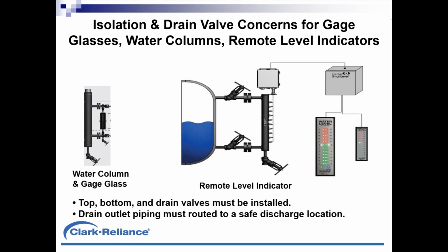Because these devices' drains are opened and these things are blown down frequently, over the years globe valves have become more commonly used. If the gate valve is not left in a full open position, with the frequent cycling of blowdowns that many operators do on these instruments, you can cause the bottom of the gate to wear on a gate valve. As a result, globe valves have become more common. We'll get more into that in just a moment.